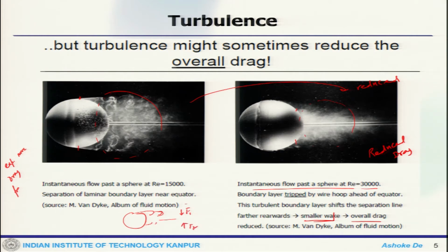These two forces will be acting in a non-equal fashion, which will create that swing. But this is one aspect of it, when the ball is traveling in air. There are other issues: to reach that Reynolds number or speed, the ball has to be thrown with that speed, then it has to hit the pitch, and that also generates some sort of lift force due to rotation and other things.